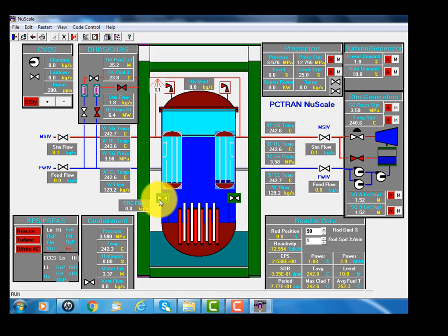Pretty soon, we'll actually see that containment water. There are 2 recirculation valves between the containment and the reactor vessel. The recirculation valves are designed to preserve the water inside the containment. So when this level is higher than the vessel, we open these 2 valves, so the water will go back into the core. You see, physically, the water level is above the top of the fuel.